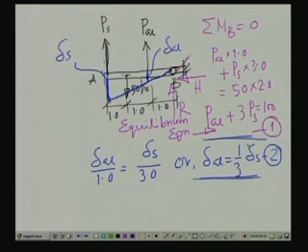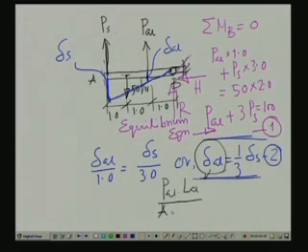Now, the next thing we will have to do is impose the constitutive relationship. That means, first we write this deformation in terms of strain, and that we relate to the stress. So, if we write this in terms of load, or rather stresses, we can say that P aluminum times length aluminum divided by A aluminum times E aluminum, this is the deformation of the aluminum bar.